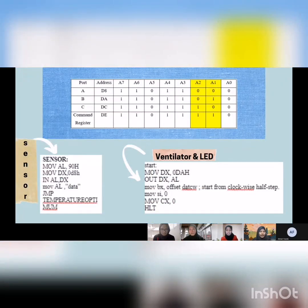Our control word 90H is obtained from the input and output connection to the PPI, and the port addresses D8H and DAH are obtained from pin addresses A7 to A0. We only use D8H and DAH in our coding since only port A and port B are connected to input and output. For the sensor part in the coding, since port A is connected to the temperature sensor, it has 0D8H as its address, which was stored in DX.